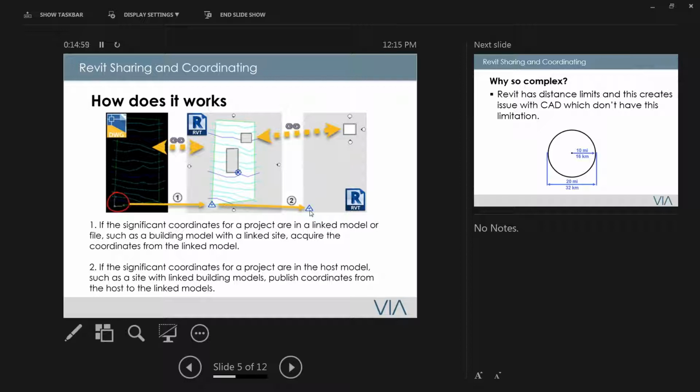It doesn't really work. The reason why I say it doesn't work is that in AutoCAD reality, your origin point is not here. It's like miles and miles away. They're always going to be using geodetic, okay? So geodetic means that the origin point is miles and miles away, but what Autodesk is trying to simplify is that, oh yeah, your origin point is that particular corner.